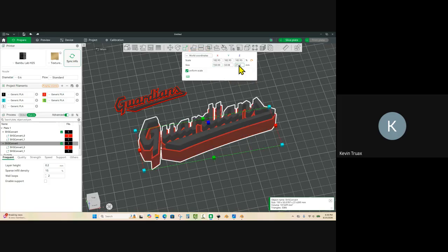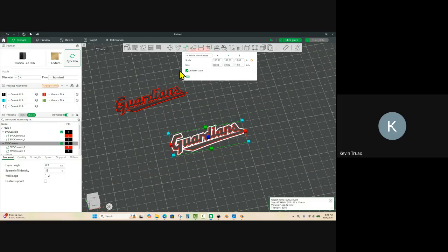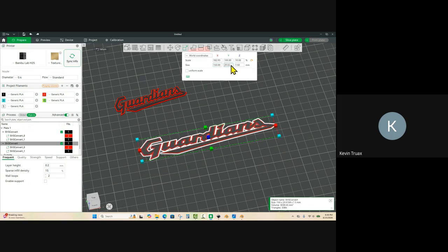okay, look what happens. Now it's 27 millimeters thick. That's not going to bend very easily on our lampshade, right? But I want you to pay attention to this value, 5308. Okay, we're going to undo that. So hit Control Z, and now we're not going to do uniform scale. We're just going to type in 150, just like we did before. And then we're going to manually type in 5308.